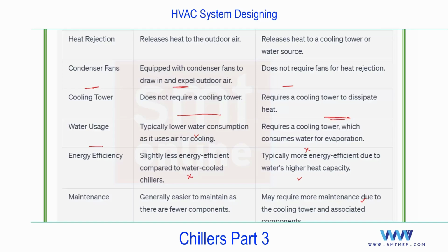So water means the chance of corrosion, and cleaning is required. And this cooling tower, all these components, so proper or regular maintenance is required compared with the air cooled chiller. From a maintenance point of view, you'll find more maintenance in water cooled compared with the air cooled.